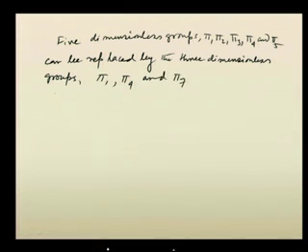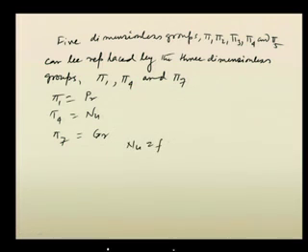So, what is pi 1? Pi 1 is, already we have seen, the Prandtl number. What is pi 4? Pi 4 is nothing but the Nusselt number. And what is pi 7? Pi 7 we have seen as the Grashof number. So, finally, our target, that we can say from these, is that the Nusselt number is a function of the Grashof number and the Prandtl number. Now, what is this Grashof number?